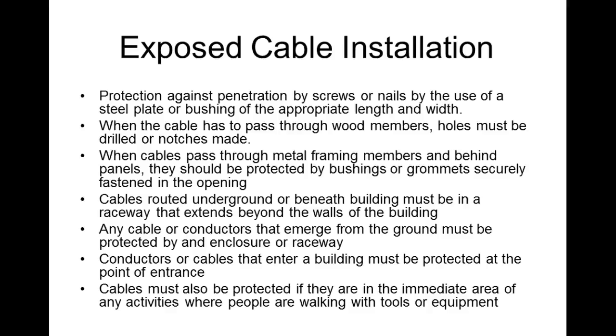So some places you have to use rigid conduit. Some places you can use EMT conduit. We like EMT. This is all EMT that they got running on the wall over there, because when we get to these joints or these places that we need to change altitude or move it away, we can bend it, right? If you take the commercial wiring course, part of that class is learning how to bend that conduit. You see these electricians did a really good job of bending those conduits and making their measurements to make it come out exactly the way it's supposed to be.